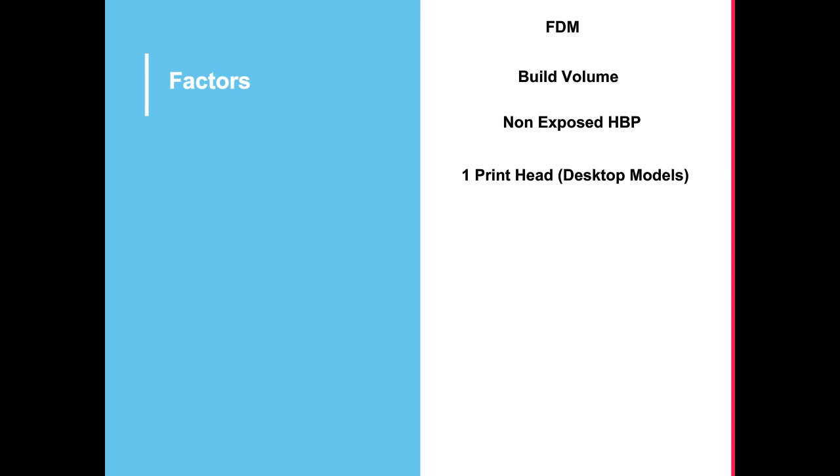But we found that when you have a printer with multiple heads that's not a professional grade model, a print that used to take an hour doesn't take 2 hours, it might take 4 hours. So the time it takes to print a model with 2 different colors on these lower end desktop models, I would suggest, with the technology currently, to stay away.